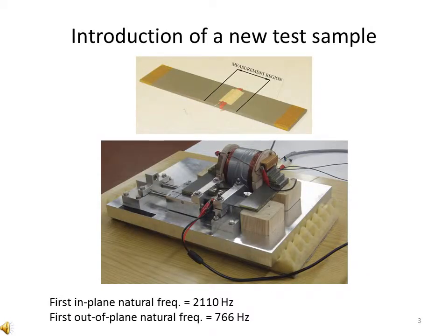With regards to the presented dynamical effects, a new test sample and experimental setup were proposed for characterization of magnetostriction resulting from a 50 Hz alternating magnetic field. The dimensions of the test sample were set specifically to assure sub-resonant operation during measurement. In-plane and out-of-plane dynamics of the system were analyzed theoretically as well as experimentally.